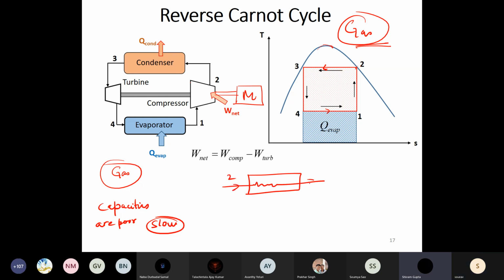Okay. So why we assume P3 equals P2 is we are neglecting the viscosity of the working fluid itself. So we forget about the viscosity. We forget about our friction factors that we have studied in fluid mechanics. We forget about f equals 64 by Re or the Moody diagram that we have studied, that for any pipe flow, the fluid will have pressure drop because of the property viscosity.